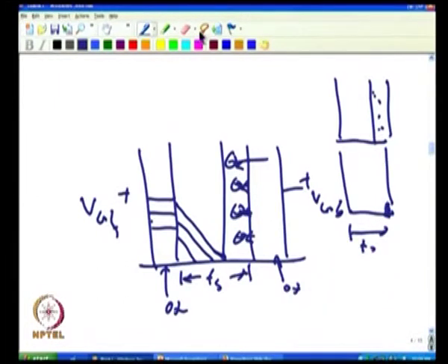Up to this point, depletion electric field is from right hand side, from here left hand side. So, electric field comes down like this. Okay. I think I better take a different color for that. That is like that, electric field. And if I take the electric field from here, that is like this, because of the back gate bias. So, that is plus higher here, 0 here. So, you have got a region where the electric field is 0.